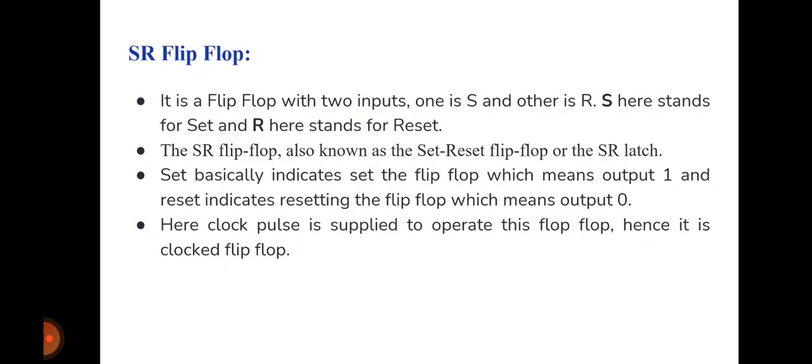The SR flip-flop is also known as set reset flip-flop or the SR latch. Set basically indicates setting the flip-flop, which means the output 1, and reset indicates resetting the flip-flop, which means the output 0. When the output is 1, it is called set mode, and when the output of the flip-flop is 0, then it is called reset. Here, a clock pulse is supplied to operate this flip-flop, hence it is a clocked flip-flop.